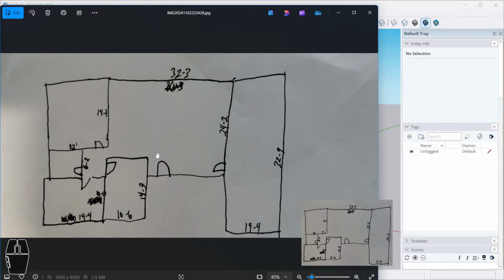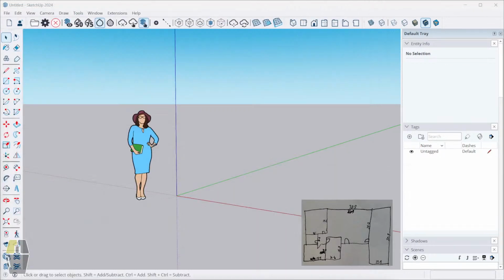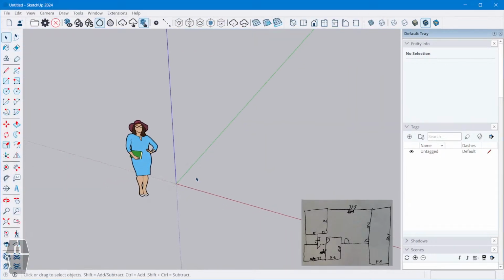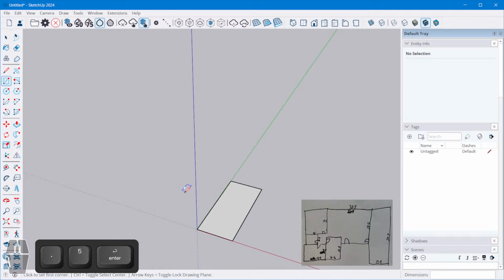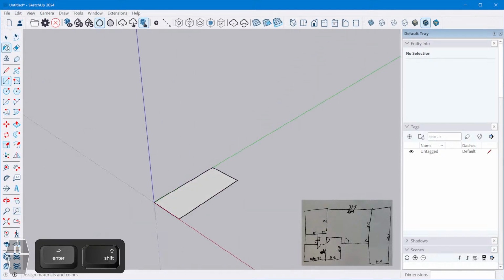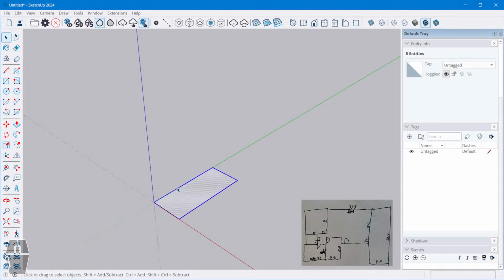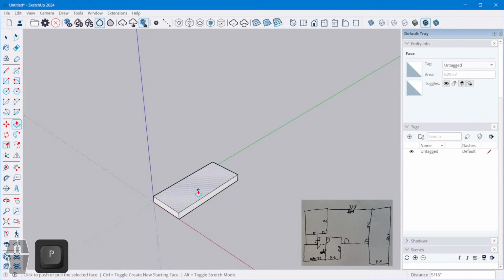Rather simple, but not too unlike what you're going to find in a residential structure. Now, this is just a regular old stick-built house. So our walls are going to be, well, this will just be easier to explain. For the wall thickness, say for our 2x4s, that is 1.5, 3.5, enter, and that's 1.5 by 3.5. So that's our stud. I'll just push-pull that up.